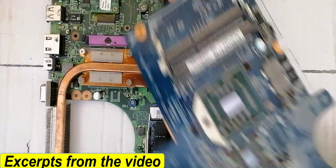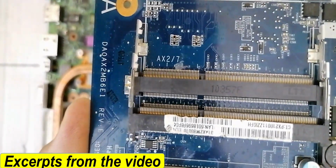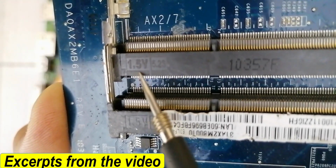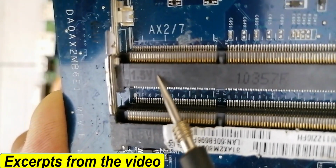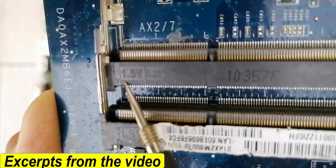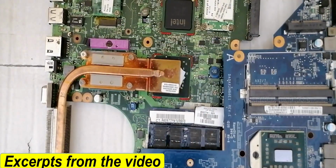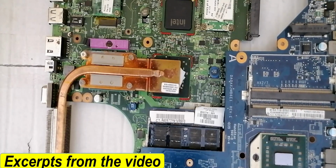Okay, I will show you another motherboard. For example, this motherboard. Let's see the slot of this motherboard. As you can see over here, we have 1.5 volts. The voltage for RAM in this motherboard means this is DDR3. So based on the voltage, we identify whether the RAM is DDR1, DDR2, DDR3, DDR4 or DDR5.